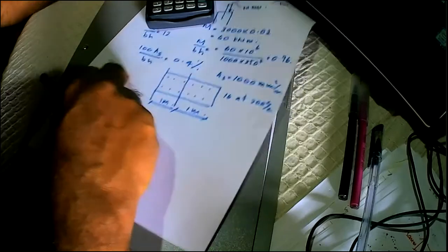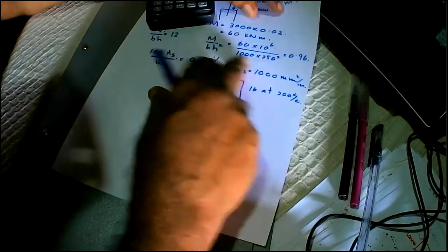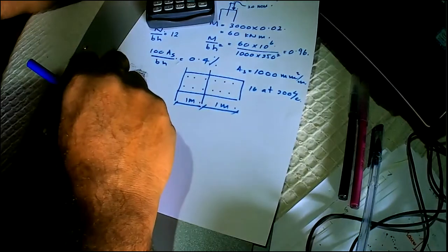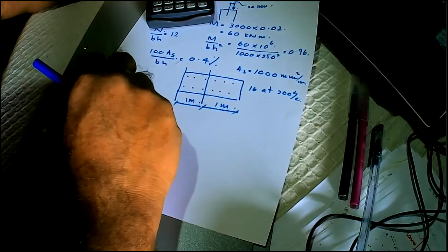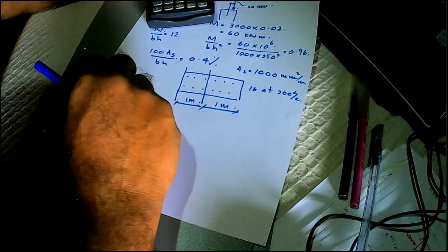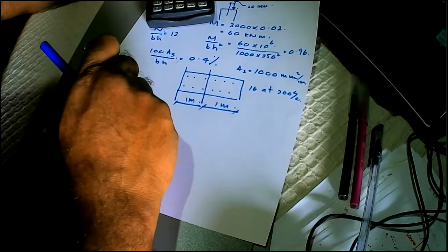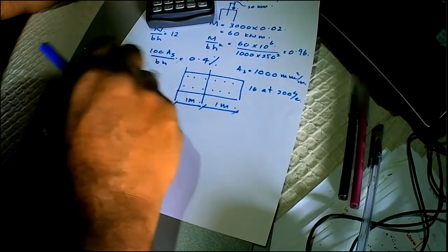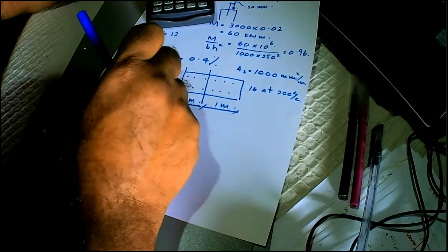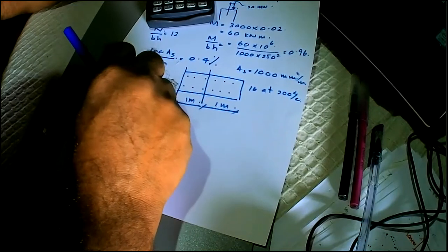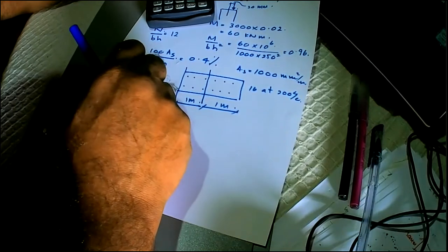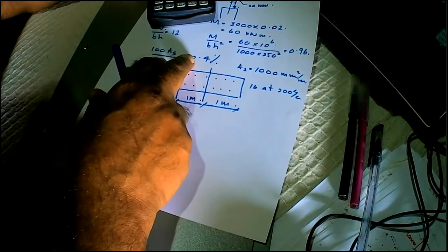In the second method, we have allowed for any out of balance, out of plane moment as well. Because if you consider a shear wall, it is very strong in its own plane, but out of plane it is not very strong. It's weak. So we have to allow for both effects. Any questions on that?